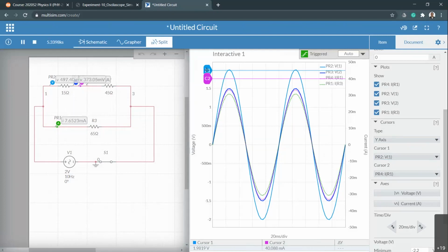Okay, very close to 2 volt. Okay, that should be close enough, 1.9897. Then my cursor number 2, it needs to be B2, so that you can see the color changes, right? It now becomes a dark blue. So move that very close to dark blue top edge.